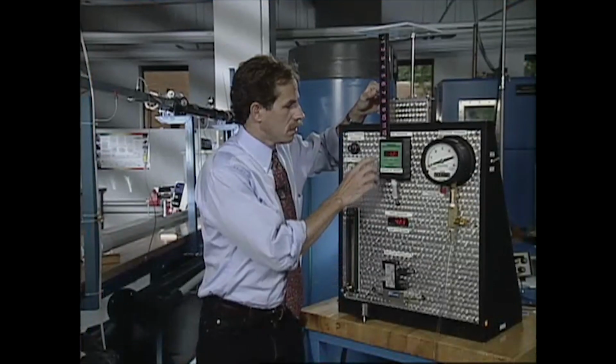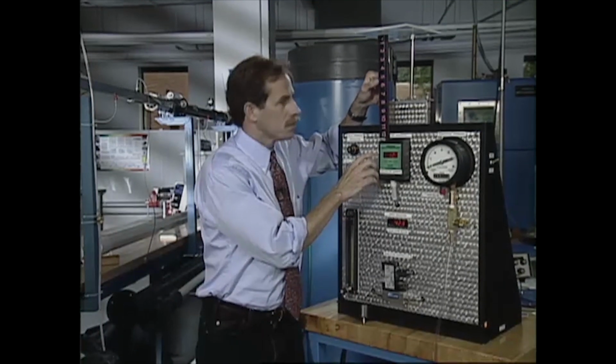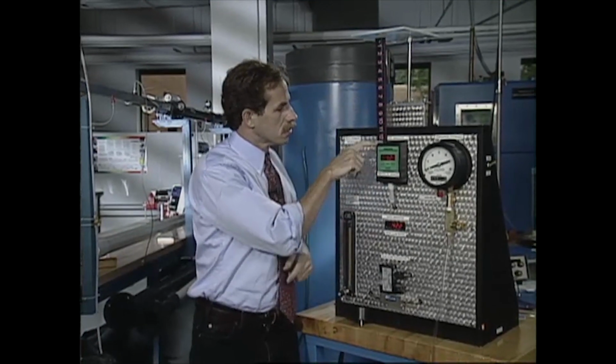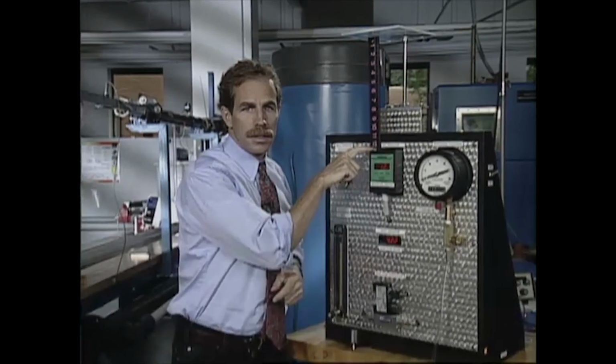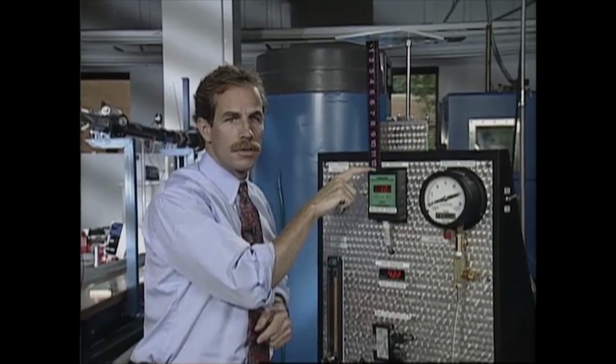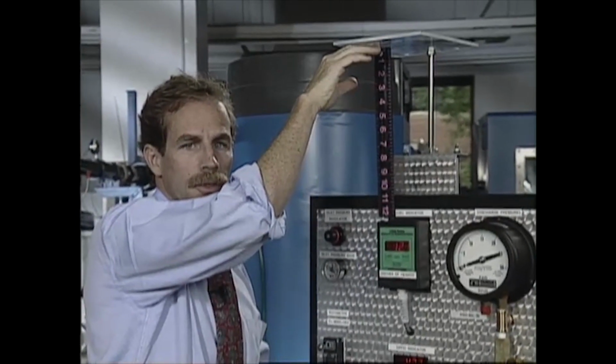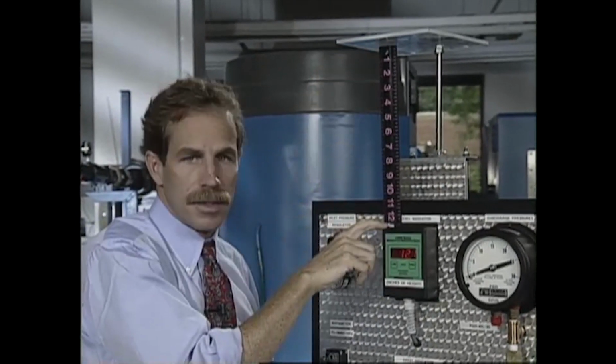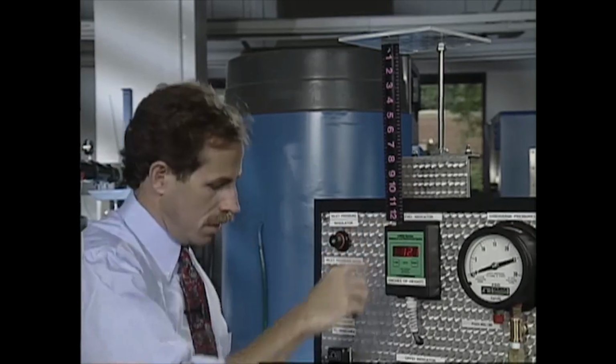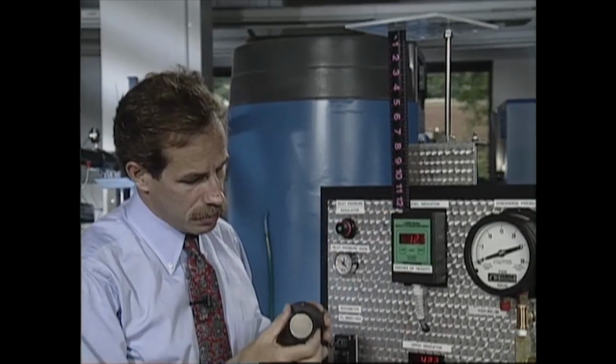Now, we actually looked at another ultrasonic measuring unit when we were down at the Omega Engineering Labs, and let's go look at that now. This is an ultrasonic distance and level measurement system. What happens here is that there's an ultrasonic transducer in the top of the unit which transmits an acoustic wave which reflects off of the object we're trying to measure and comes back down into the unit. The transducer actually looks something like this.